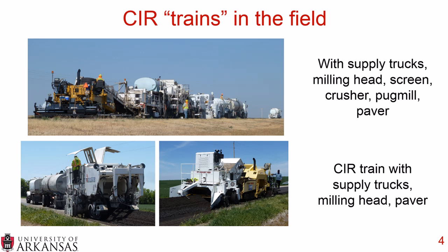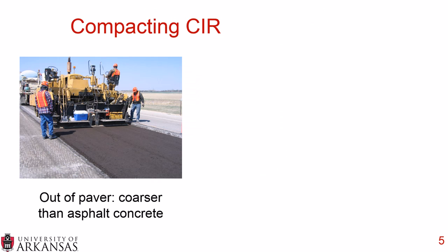Once the material goes through the paver, it comes out the back of the paver. And if you've ever been on a hot mix asphalt job, you can see that this is a little coarser than asphalt concrete. It does not look like an asphalt concrete mat. It looks like a CIR mat.